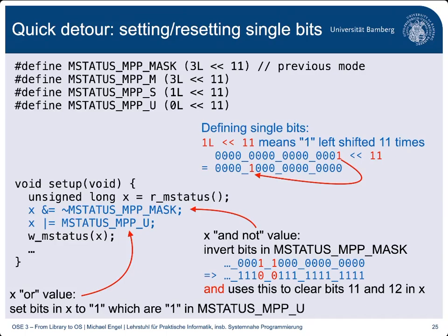Yeah, so essentially a 64-bit value for our RISC-V. If we shift this 11 bits to the left, this means our 1 here is just shifted to bit position 11 instead of 0. And this is a very convenient notation simply to avoid putting arbitrary hexadecimal values which represent the same bit values there. And now you can add a bit to a value by ORing it.